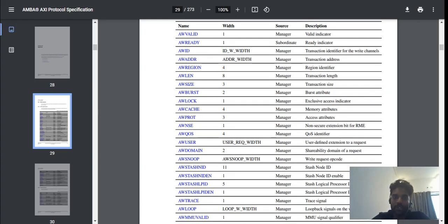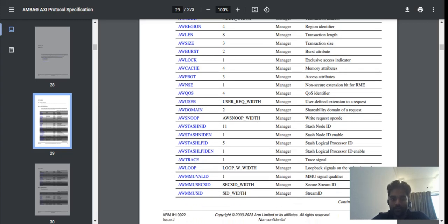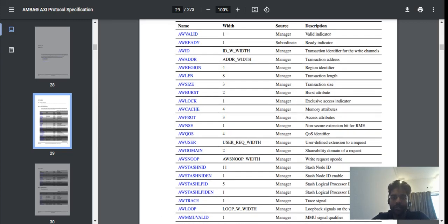So these are the different features. What is the size? What is the burst length you want? You can set all these things up. There are other features too. You can see many signals are there, and you can choose based on your application. You can leave the remaining signals unconnected also, it won't impact anything. So the main features, you can start using them. What is the length you want? Once you send the first address, how many bits of data you want to transfer. That's the transfer length, and the transfer size, and the burst type. These are the basic use cases.